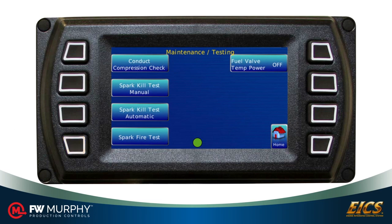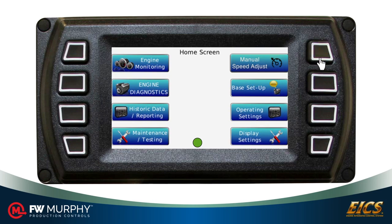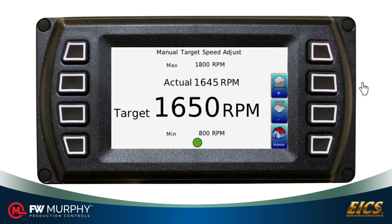Maintenance and testing. On this screen, while the engine is stopped, you can run a compression test on the engine, test fire the spark plugs, turn on the fuel valve. While the engine is running, you can manually kill the ignition on particular cylinders, or perform an auto kill. Manual speed adjust. Here you can increase or decrease the engine speed by using the buttons.